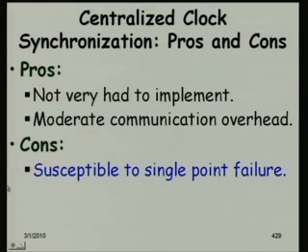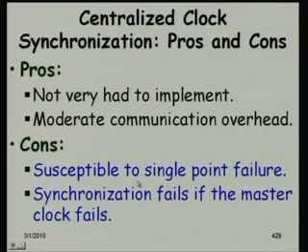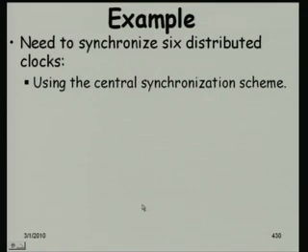But one major problem of centralized clock synchronization is the single point of failure. What if the master clock fails? If your application is safety critical, where failure cannot be tolerated, then this centralized clock synchronization is not a good solution. The clocks will fail if the master clock fails.